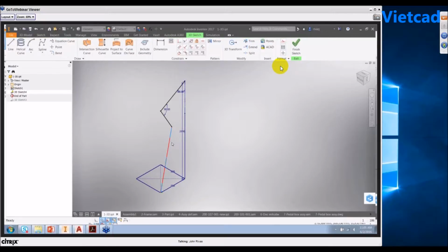The new constraints that are available in Inventor 2017 enable you to align your sketches, whether it's going to be parallel on the Z-axis, or let's say on this particular sketch, I want to align it on the XZ plane, or rather the YZ plane. So I can adjust my sketching here, like so. And then from here, I can simply use this sketch for my next design.